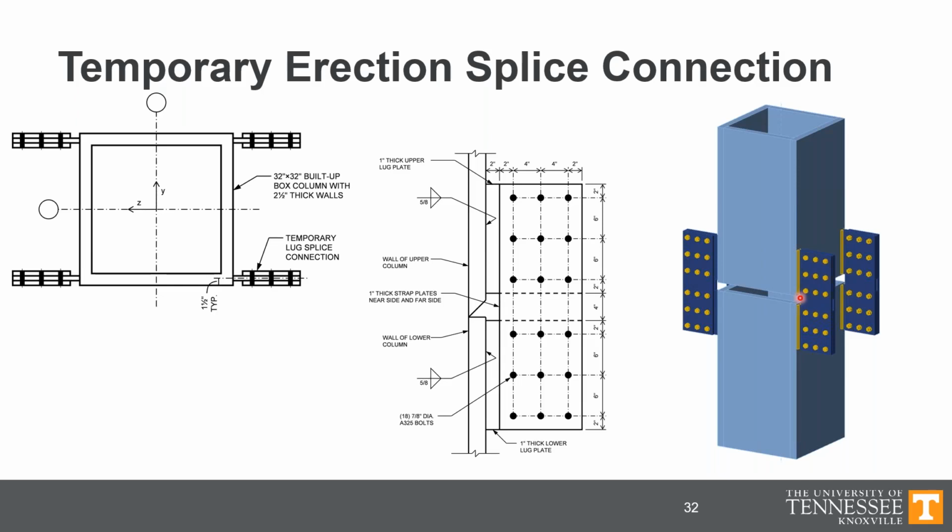As well as the process of getting the results necessary to make informed decisions in design. This connection is not a standard form, and it also doesn't have standard loading. It's got actually some pretty complicated loading. It's got axial compression, shears in two different directions, bending moments in two different directions, as well as some twist.